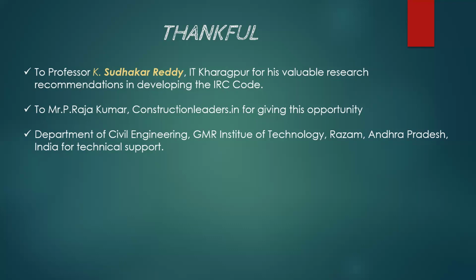Yeah, that's true. So I want to understand two things here: whether this test is stress controlled or strain controlled. That's one thing. And whenever we apply this test to unbound material, normally granular, and some pavements where we have cement-based sub-base layers, there we have more variation in the test stages. Yes, whenever you have cement-based layers as granular layers, definitely a lot of variations will be there. So finally, we decided not to go for the cement-based layers. Now we are applying it only to others; some developments regarding that will also come, I think.